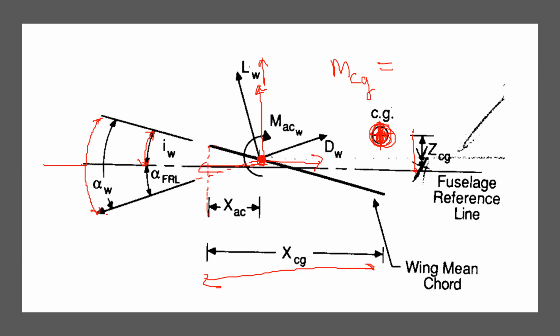Then for the vertical components of forces from lift and drag, this distance becomes the moment arm, right? So let's call it some force F1 times this moment arm, let's call it some length L1. And for forces that are acting horizontally, for these components, this length L2 becomes the moment arm. So all you have to do is add the remaining forces, let's say force F2, times L2.